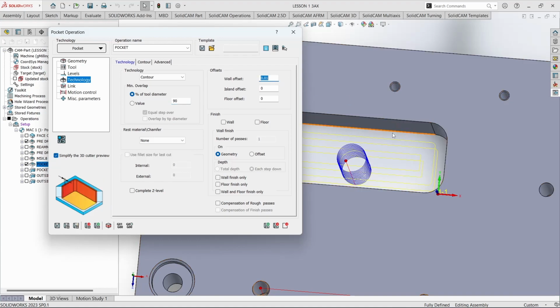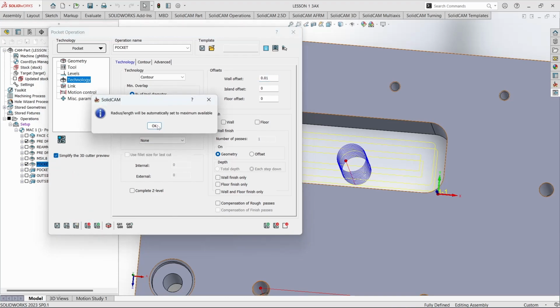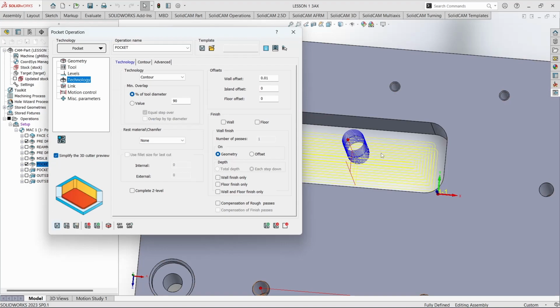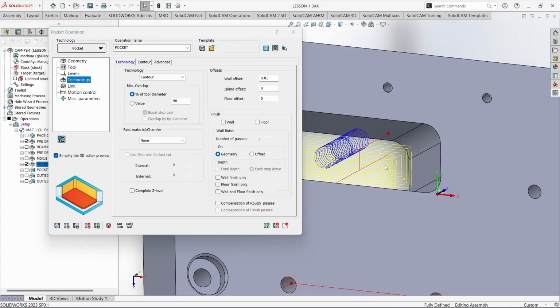Okay, in here, since this one goes through the pocket, you want to leave some material for the wall, right? And then finish. I mean, if you check here, it will do another pass, but I make a new one, so I can show you that later on why I did that. Okay, see, that's why step over is smaller, because you don't want to rub too hard, right?